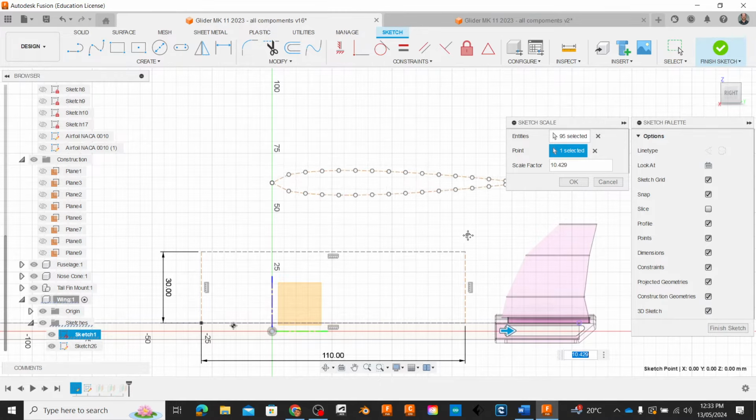So sketch 2 is the next one that I want to manipulate. I'm not going to do any scaling with this one. I'm going to leave it as is, but I am going to change the angle of attack. So here I'm going to go right-click, edit sketch. I'm going to select this sketch, modify, move copy. Just click once on this rotation bar, and Z angle minus 5 degrees. I'm going to change that to minus 3.5.